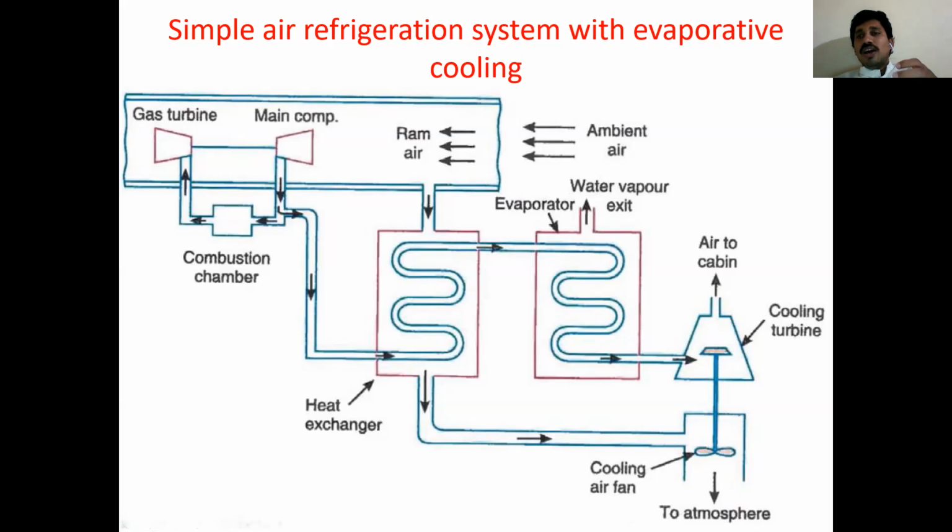Due to that heat transfer, this medium will be evaporated. The name already tells you: evaporator. It evaporates one fluid, which may be water, ammonia or alcohol, whatever it may be, at low pressures. So you have to see the saturation temperature at the required pressure. At sufficient pressure, we go for evaporation. Finally, that will be supplied to another application.